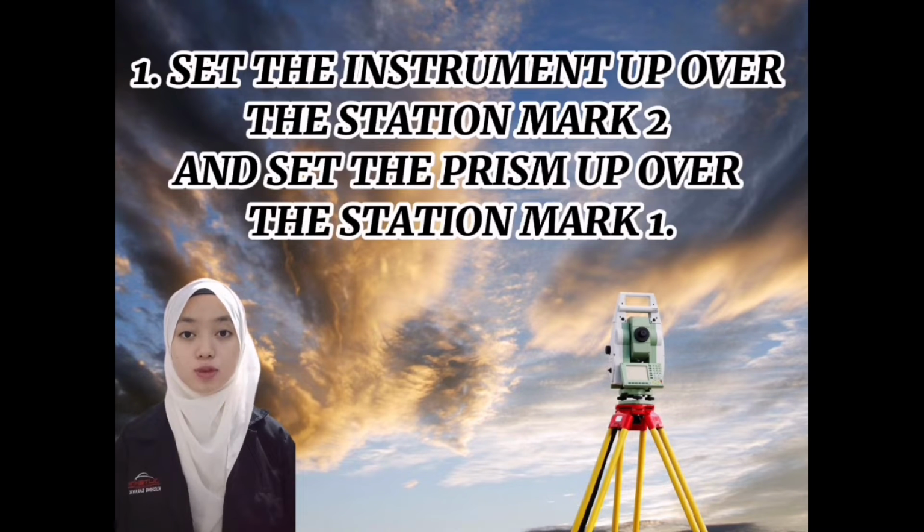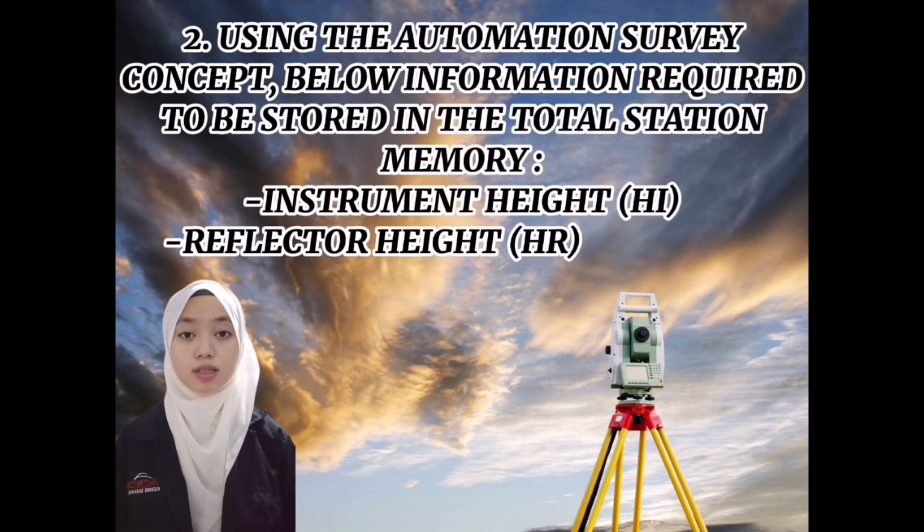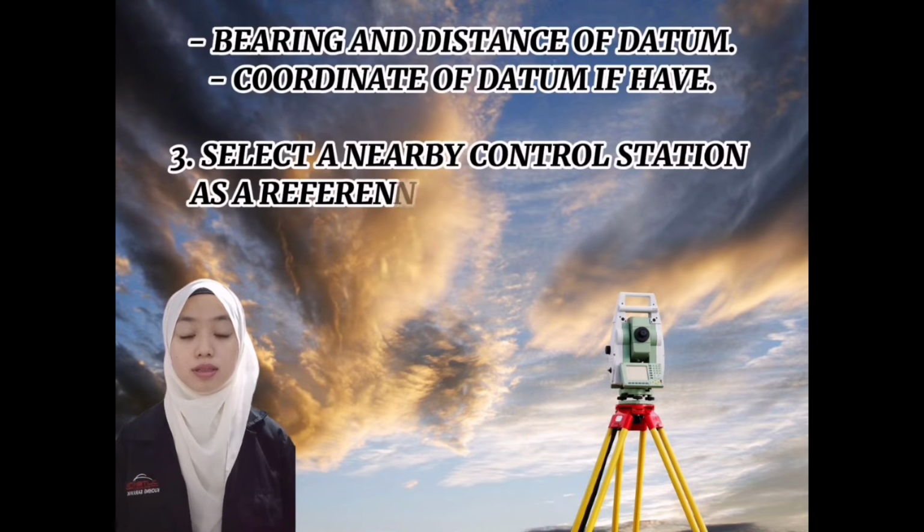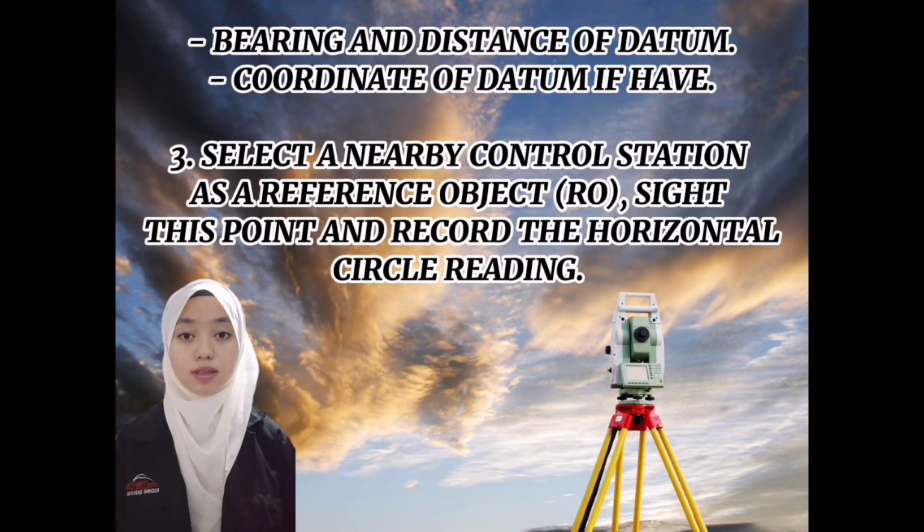First, set the instrument up over station Mark 2 and set the prism up over station Mark 1. Second, using the automation survey concept, the following information is required to be stored in the data station memory. First, instrument height HI. Second, reflector height HR and mini prism height HR. Third, bearing and distance of datum and coordinate of datum if available.